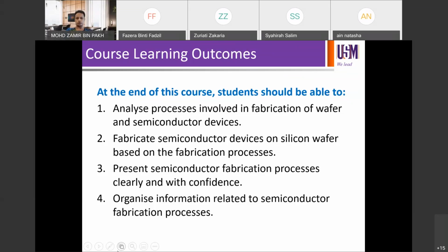What if you use subtractive etching or additive etching just now? What if you use isotropic etching or RIE first, the one that we did in our case study last time, a couple of approaches where we discussed double patterning and also the isotropic plasma etching process, right? So you should be able to analyze the difference and the properties and how it looks on the wafer, what the impact is, so what you should expect as the results.